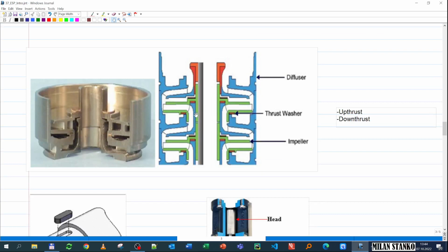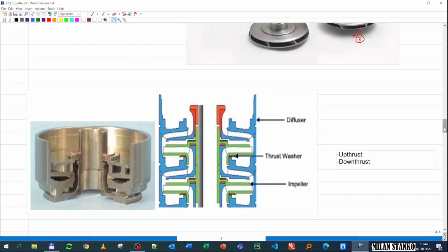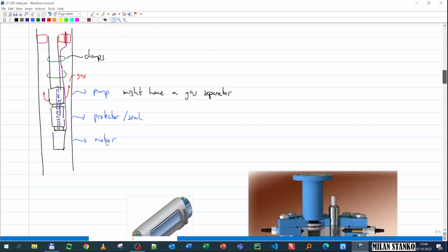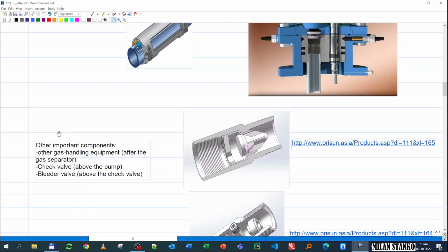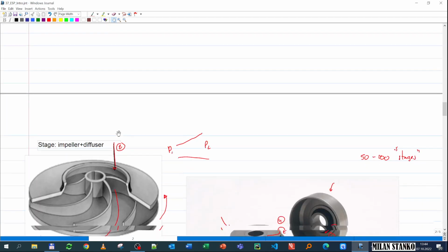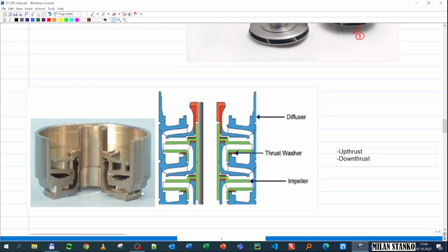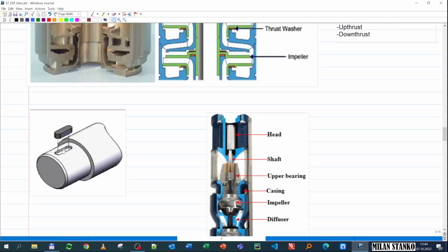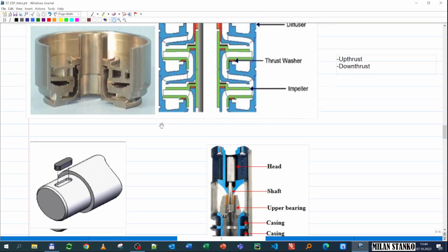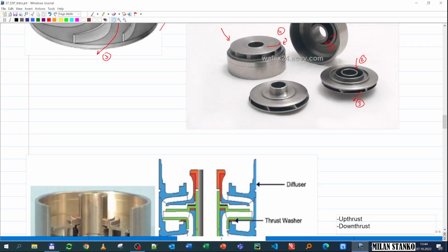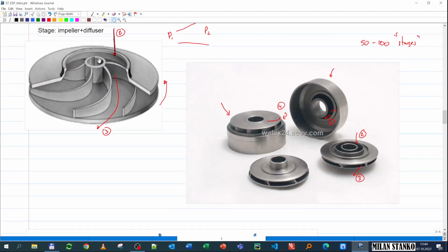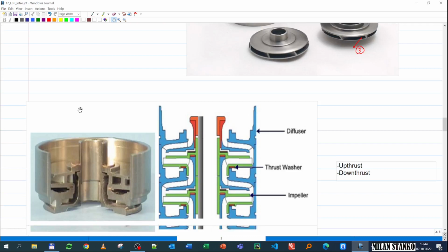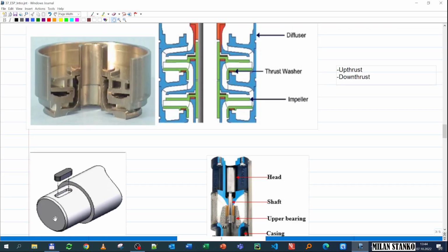So the way that this impeller rotates, I mentioned earlier that the motor has a shaft that is sticking out and is passing through the whole assembly, and that shaft is rotating. So to make all the impellers rotate, you use a key mechanism. That is, you make a hole in the shaft, and you make also a hole. I think you can see it from here. You have a small dent in the impeller here, and also here. You can see the impeller, and then you put a key in between that is joining the two of them,